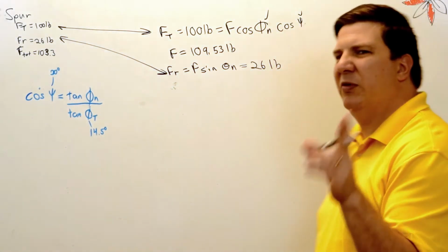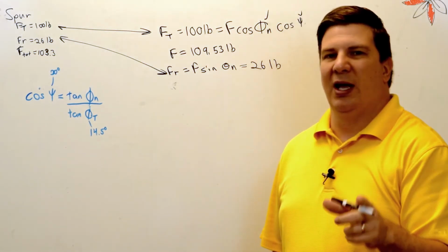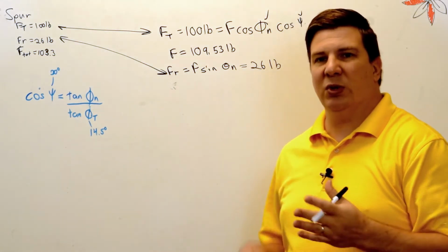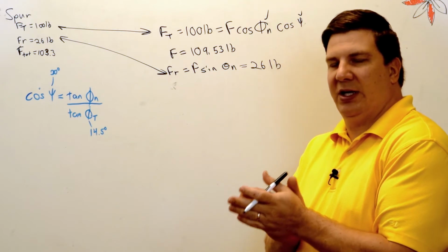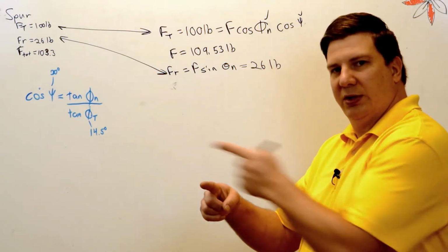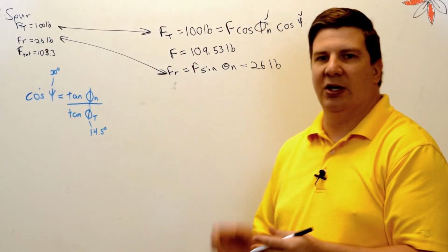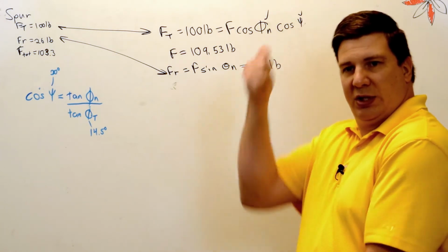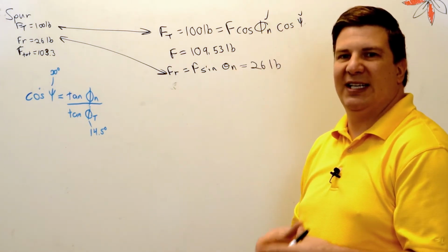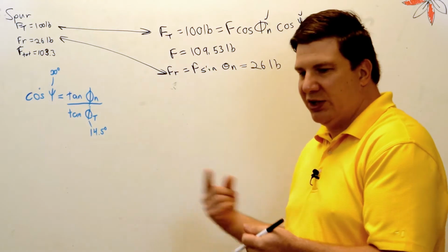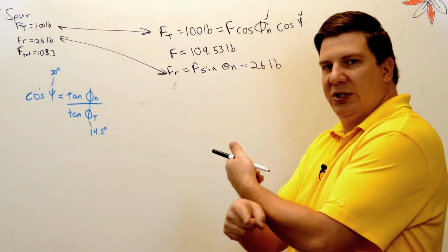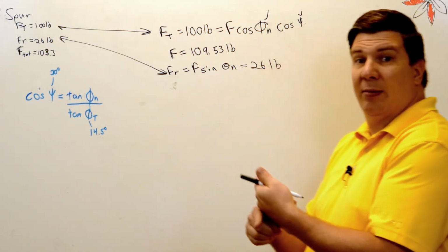Now before we go calculating the total, we now cut those gears at an angle. So we're going to get not only the tangential pushing against the end of the gear, and the radial pushing apart, but we are actually going to get an axial force shoving the gears sideways, and they're obviously shoving each other in opposite directions.